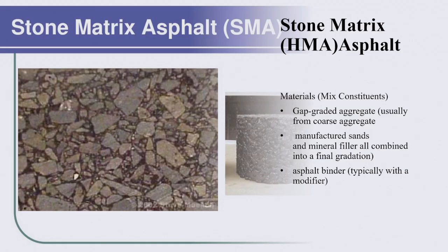So stone matrix asphalt, again, as I said, gap graded. Manufacturers combine the mineral filler into the final gradation, so that has to be considered. And then for the asphalt binder, you could use a modifier, because workability is going to be a function of the voids.